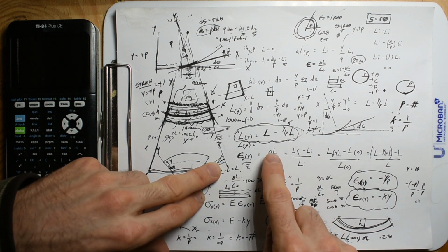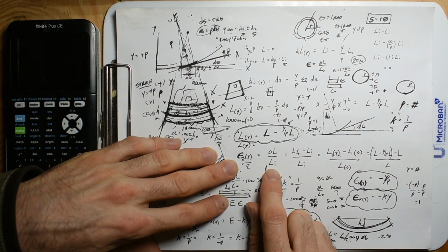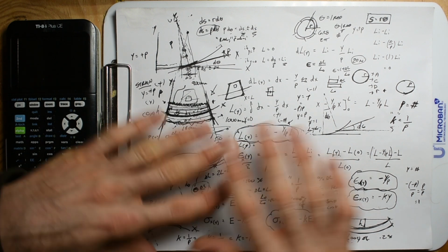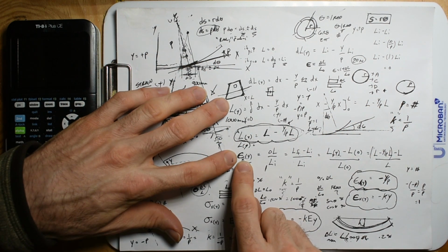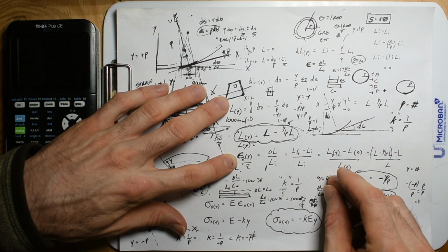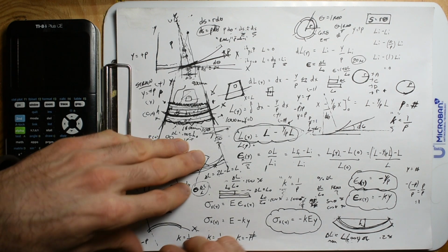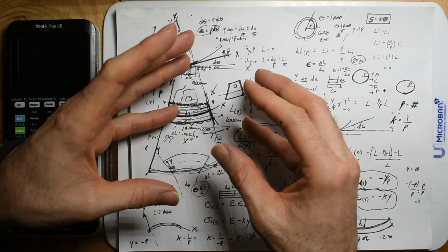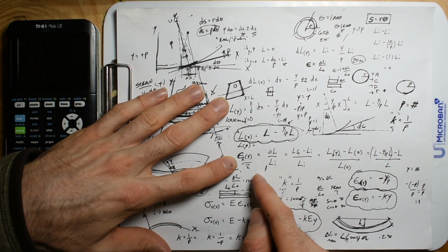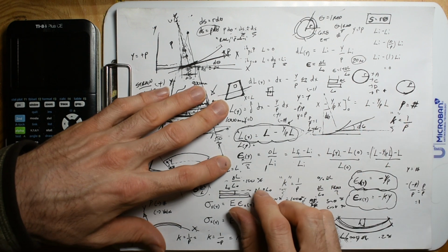I can't change its length by 3 millimeters. Let's say bad things happen at that point. So I can't use 0.003. So 0.002 is the extreme limit. But this is a moving value, while I can say that's a stationary value if that's the max. So strain for steel is 0.002. But if I'm just out there and I'm stretching some steel, maybe it's 0.001, 0.0005, like half of 0.001.